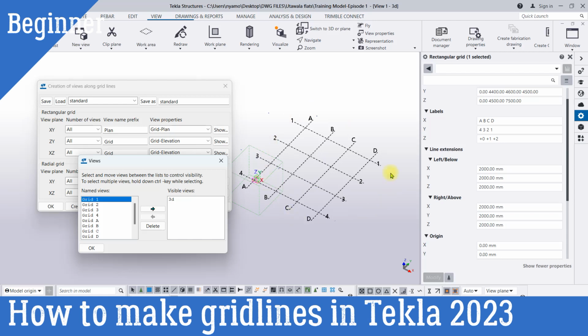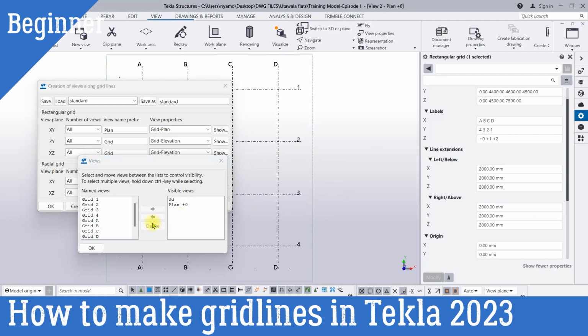So the reason why we want to convert this to 2D grid lines is because sometimes you might want to find a detail at grid 1. If it's a beam at grid 1, it's easier for you to use this kind of view because it's easier to touch that particular beam or column at that point. Because sometimes you'll find that it is difficult to choose one in the middle if you do not have this grid line. So for the purpose of demonstrating this, I'm going to choose only plan at 0